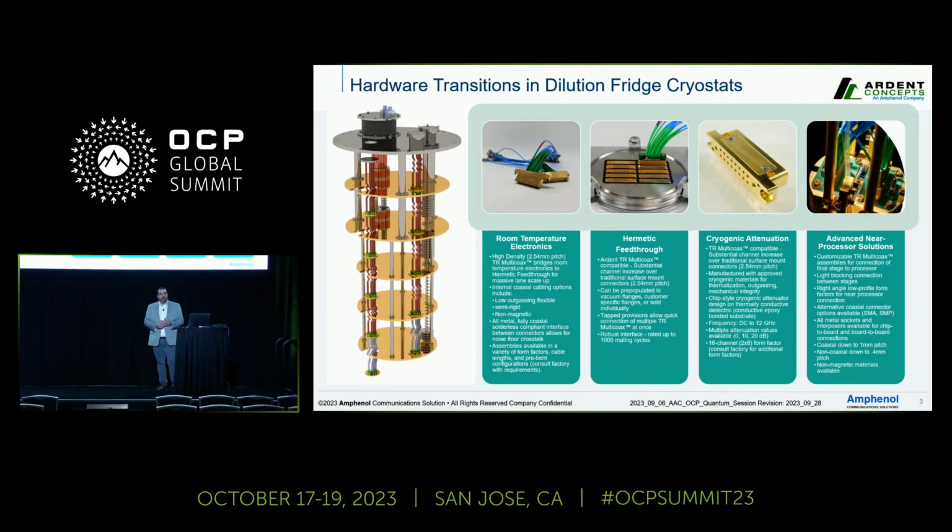Exploring the inner workings of a modern quantum computer, we find critical hardware components that enable practical installation and adaptability to ever-evolving architectures. While not explicitly depicted in this illustration, quantum computers critically rely on an abundance of room temperature control electronics, which are typically housed in a rack and stack configuration. These control electronics can come in various form factors, from traditional PXIe style designs to highly customized front panels, with all solutions geared towards increasing and maximizing RF connector density at the front panel.